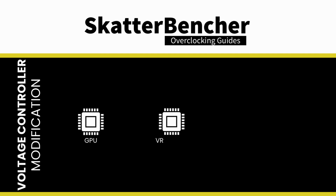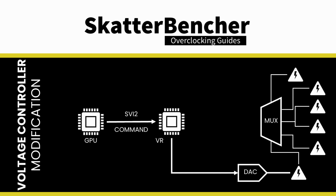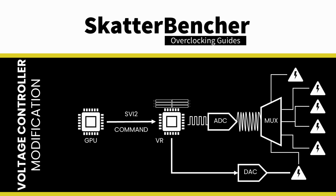The GPU sends VID commands for the GPU voltage to the voltage controller via the SVI2 interface. The controller then uses a DAC or digital to analog converter to set the voltage. Via the multiplexer, 6 analog inputs feed back information to the GPU. The ADC first converts these analog signals to digital information, which is then stored in the controller registers.